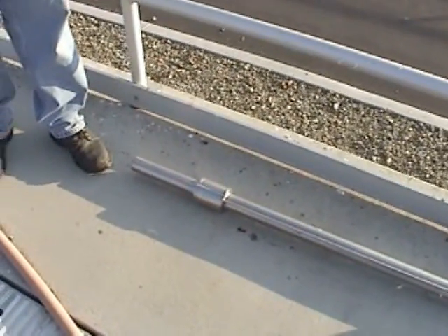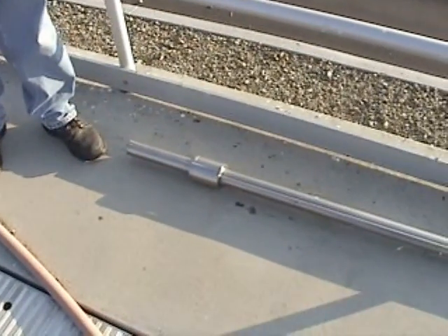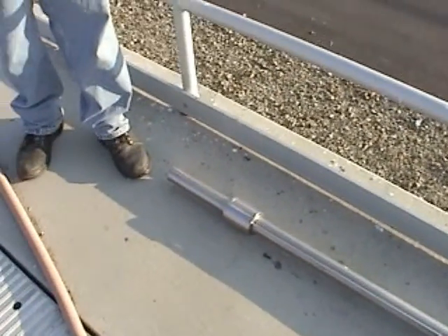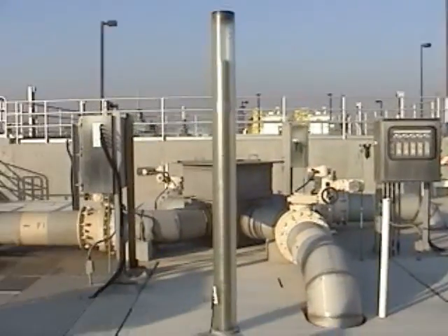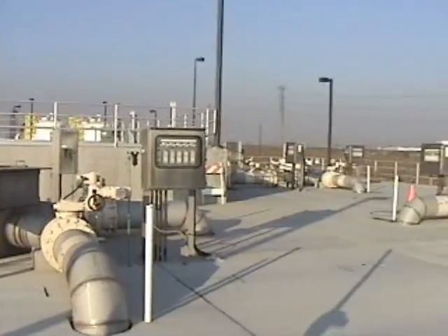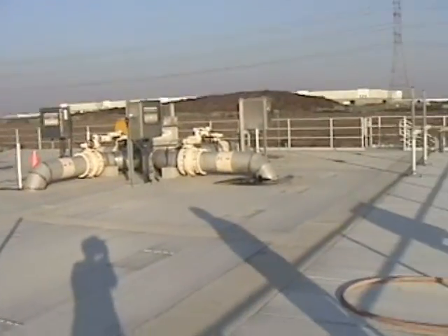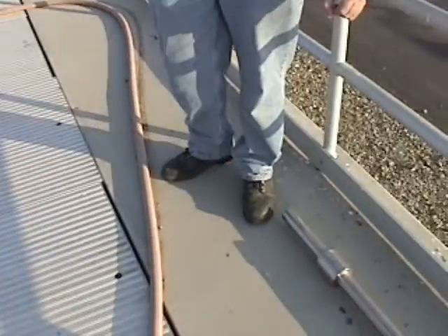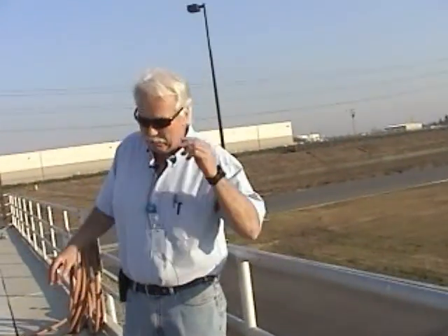So if you see debris in the secondary clarifiers, like a plastic bag or trash or whatever, if you can get it while it's easy to get, it'll save you a lot of problems, because otherwise it's probably going to end up in the filters and get sucked into one of these, and we'll have to pull it out and clean it. The bottom of the filter has a cone.